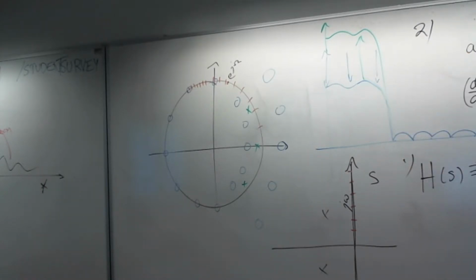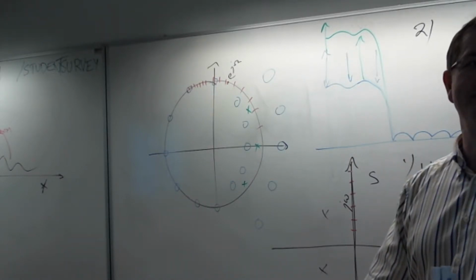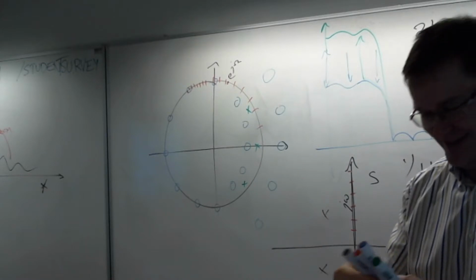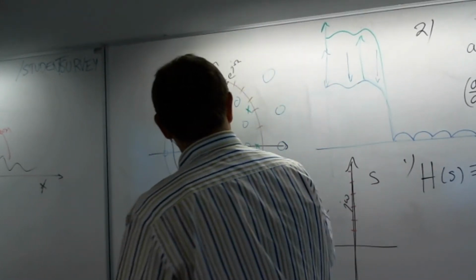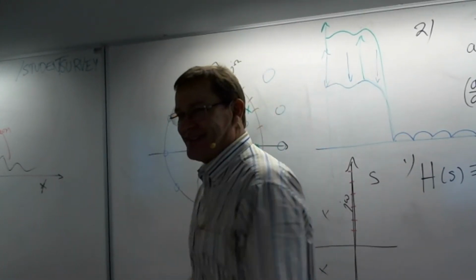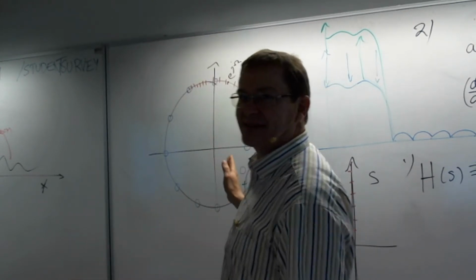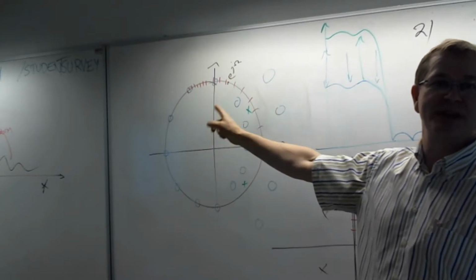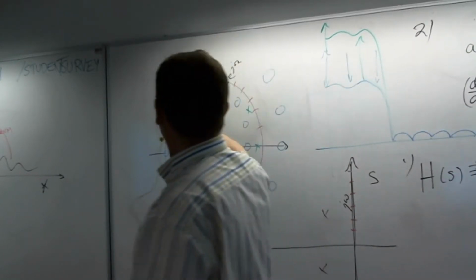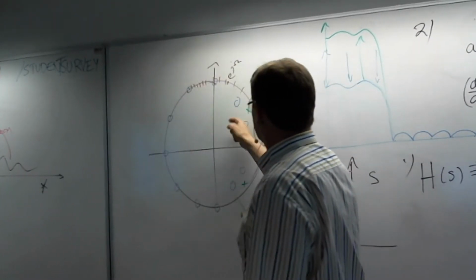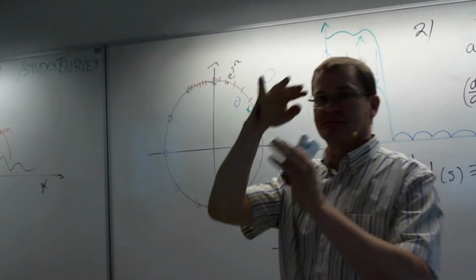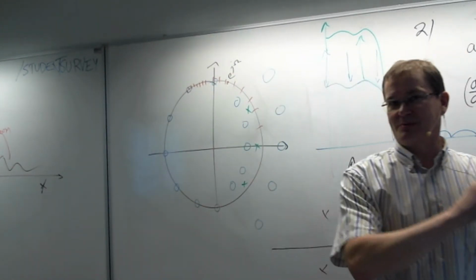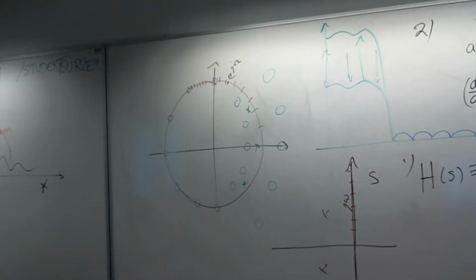And then the third one, direct design. It takes some balls to do it. Okay, so this would be direct design, meaning that you just start putting the zeros and poles on the positions you think they would be in the first place. Then you start wiggling these parameters a little bit to match exactly what's supposed to be your filter design.